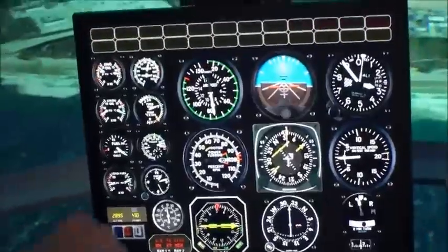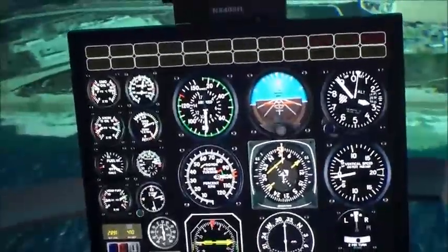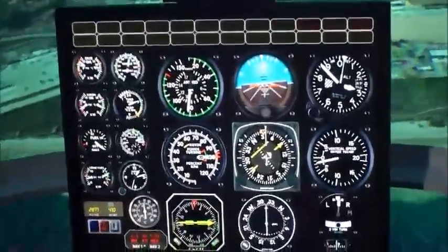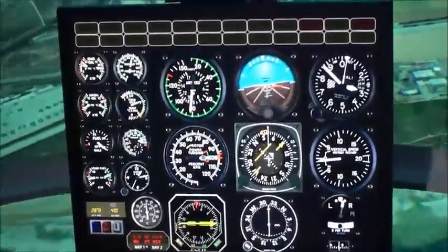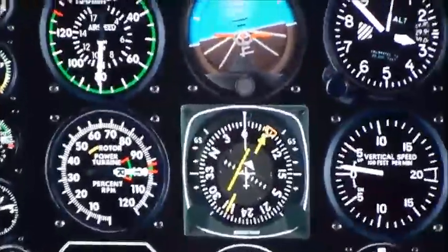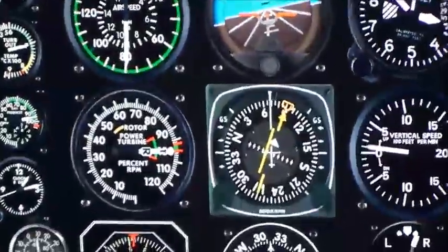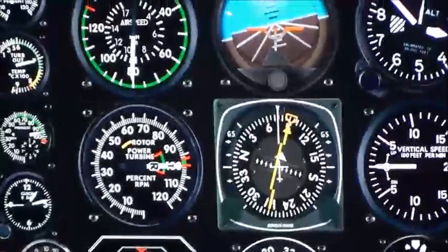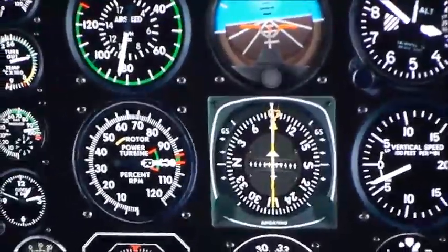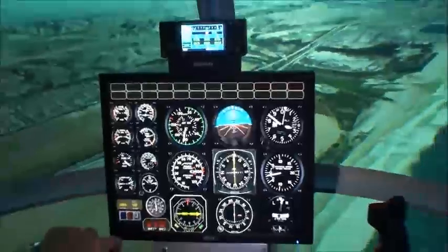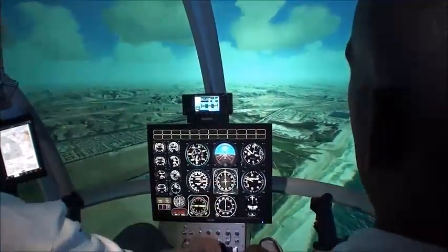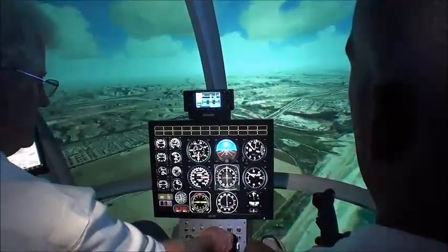Just like you did before, when you see that thing move, just put it on the top edge of this thing, put you right on it. There it's moving, so just go for it. We're closer, so it's happening faster. Nicely done. So we're about a mile from the VOR, so I'm going to put the outbound radial in here. You just keep flying on that orange bug until we cross over. Okay?